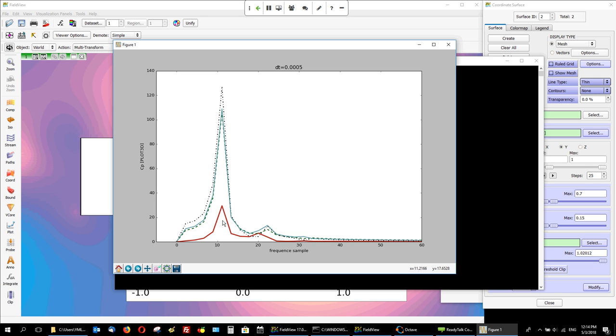And what this plot provides as a benefit is that thanks to the magnitude, you can really discriminate which are the most significant frequencies for the flow you're working with. Didn't mention it here, but each line is for 1 point on which we've followed the CP variation over time.